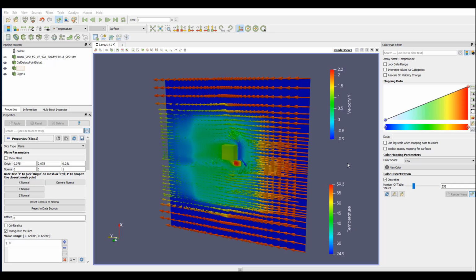Here are the CFD results for forced convection. The setup is like putting it into a square cross-section wind tunnel. The airflow comes from the right-hand side surface, blowing to the left. Then you can see the flow will be blocked by the components and PCB board.